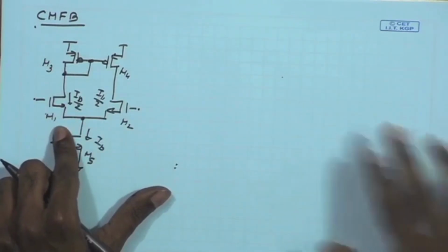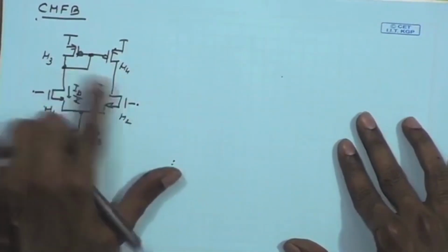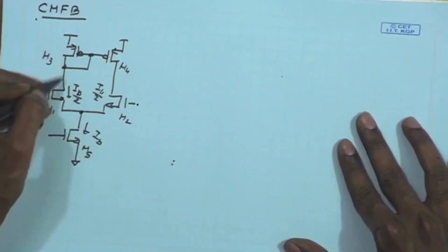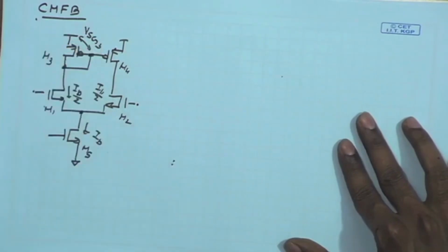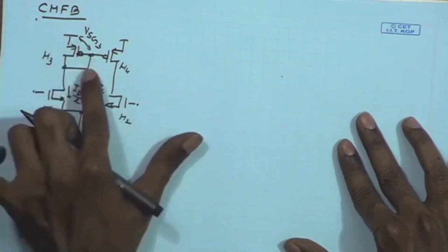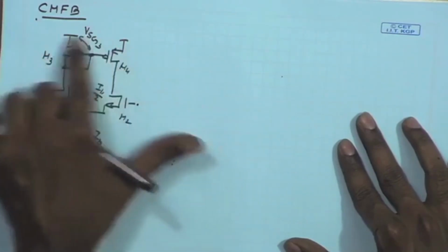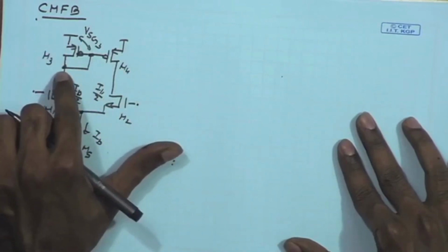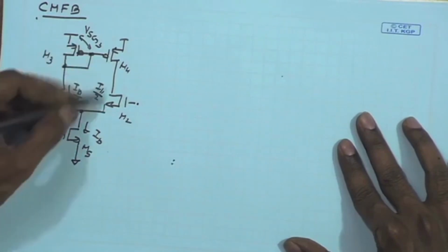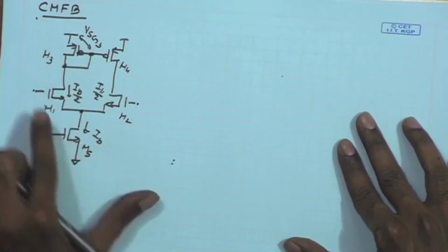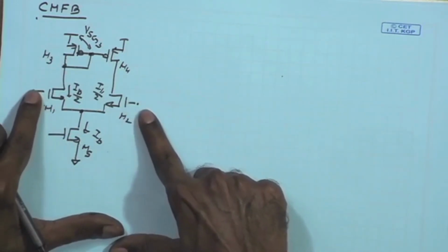and therefore, both transistors M3 and M4 are also going to have IB by 2 in both of them, and the IB by 2 flowing in M3 is going to establish a certain VSG for the transistor, which is going to be copied by M4. The same VSG applies for M4. Therefore, this load acts like a current mirror. M3 establishes a certain value of VSG, which is enforced by the ID by 2 provided by the bias current and by the symmetric biasing point enforced at the gates of M1 and M2.